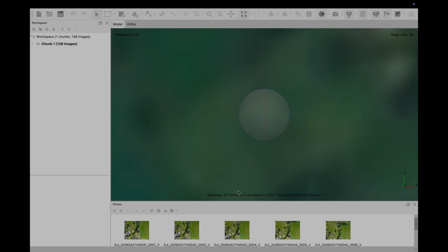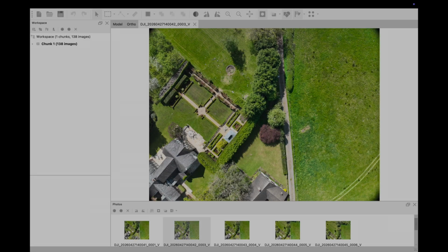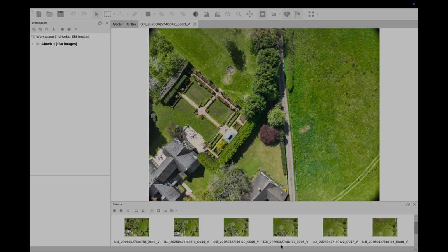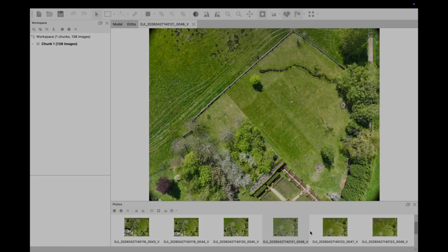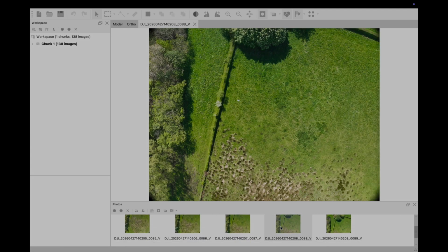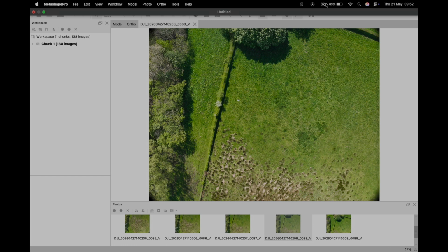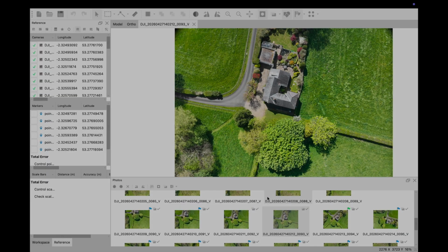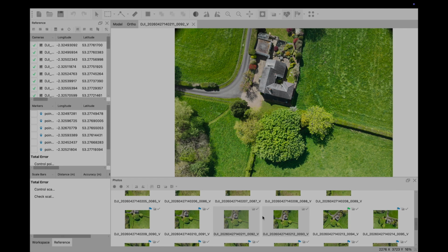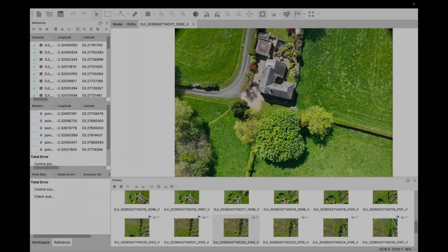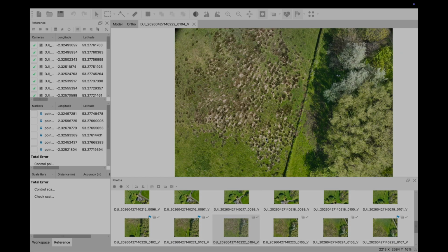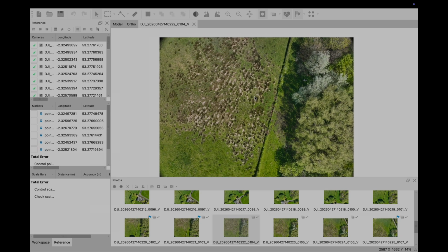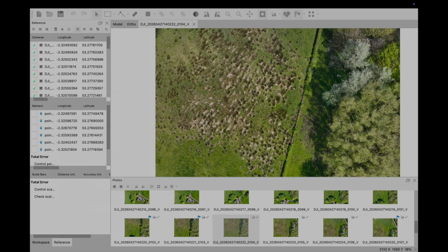What you're looking at here is a full drone photogrammetry workflow, starting with a set of overlapping aerial images captured during a drone mapping flight. Rather than simply viewing these as individual photographs, the software uses them as raw spatial data to reconstruct the site in 3 dimensions and generate a measurable mapping output. This is essentially where the workflow begins, a collection of overlapping images that will be processed into something far more useful than just aerial photography.